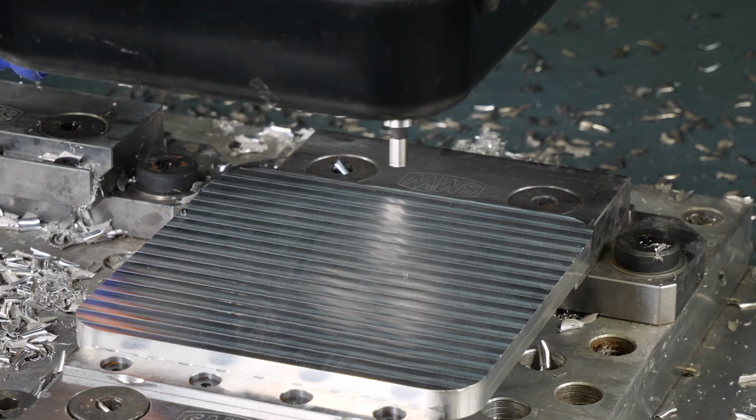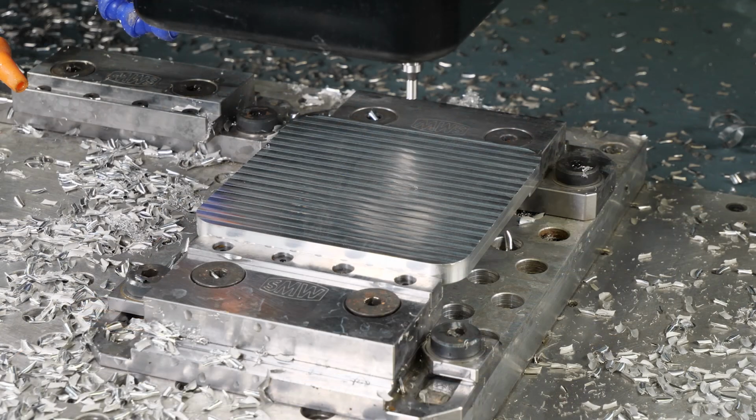Bring her up. And the same, we are in our Y. So now I'm going to type in Y, and we are above the part. So we need to tell the machine that we are Y 100 above it. 0.1, okay. And there you go. We've now touched off our part without having to use an end mill, without having to actually cut into anything.